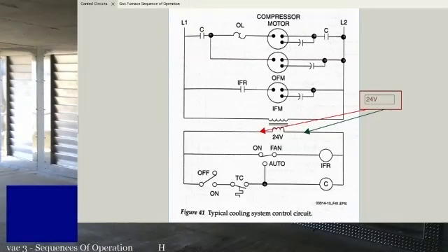So if you got float switches, duct smoke detectors, anything like that that gets added after the system, that's usually going to just cut power to the unit or cut control voltage to the unit. In case of float switches, it might only cut cooling, but it depends on the system and who put it in. Generally, I try to just go cut all low voltage on an external safety and just call it that.